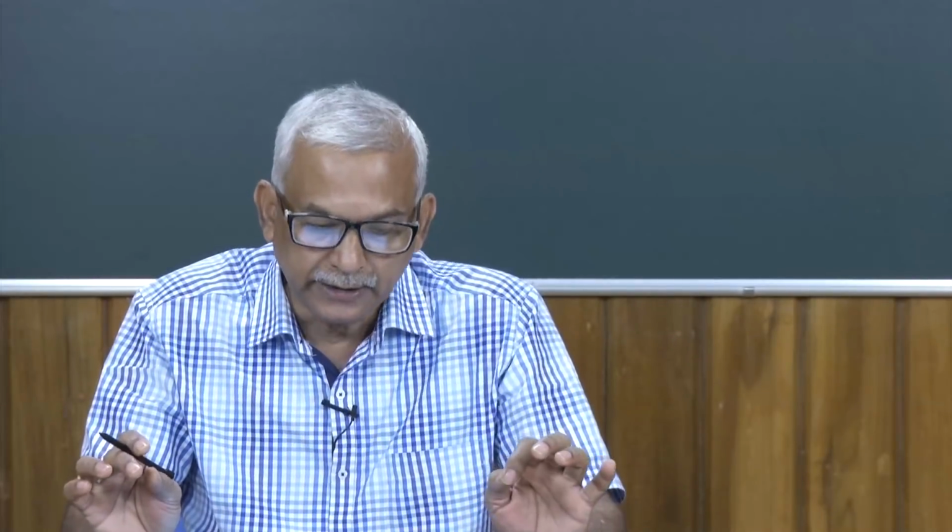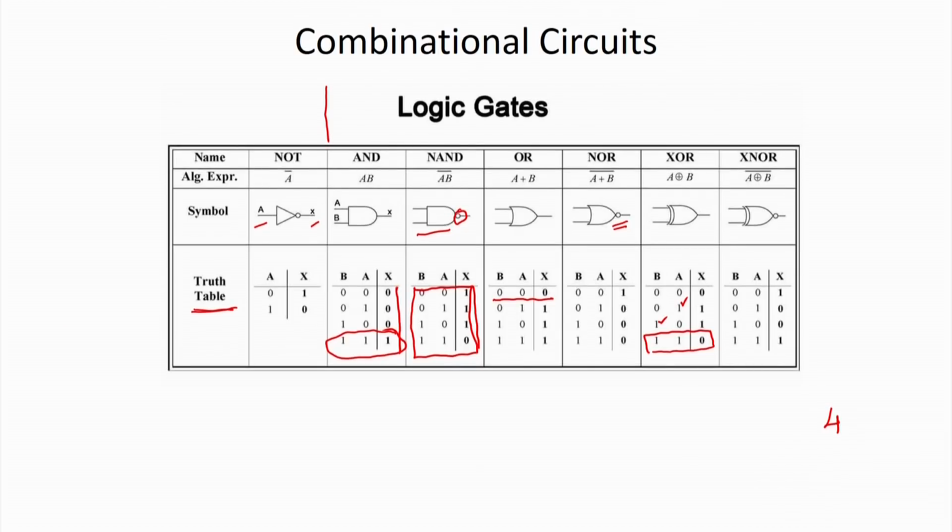Now, secondly, these gates can be extended for more inputs. Say, if I look at a gate with 3 inputs, a 3 input AND gate, it can be visualized like this. First, I take the AND combination of the first 2, and then the output we get is combined with the third input.